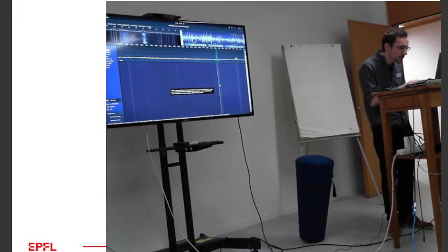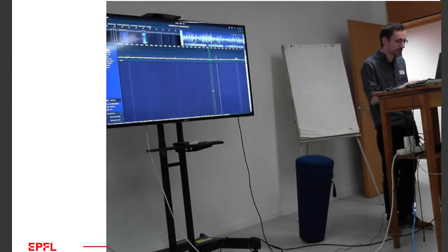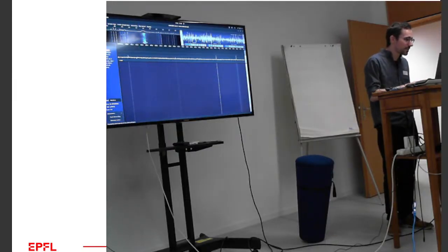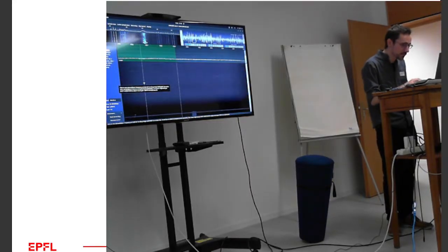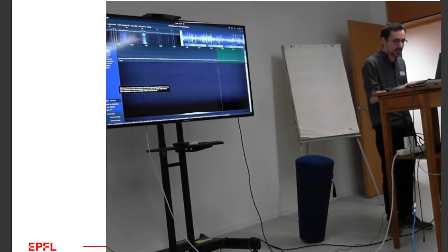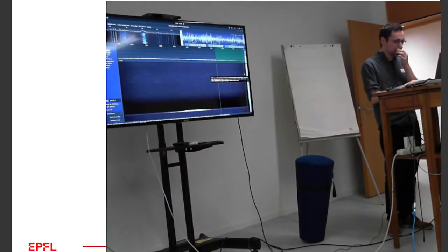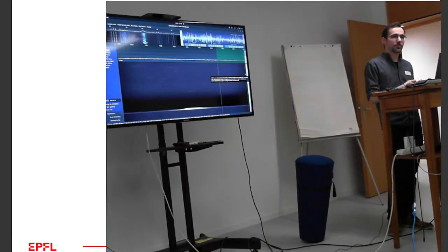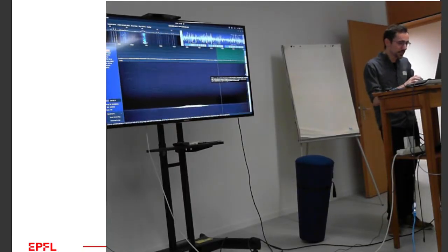So I have a LoRa transmission going on over there on 433. Can you catch this? 433, I don't know exactly what frequency. There's a packet every second. Yeah, that's probably that one because it looks strong. Nice. And if I reduce the sampling rate, you see it. Okay, so that's the LoRa packet. It's just one value being transferred, one value every second, a counter counting up.